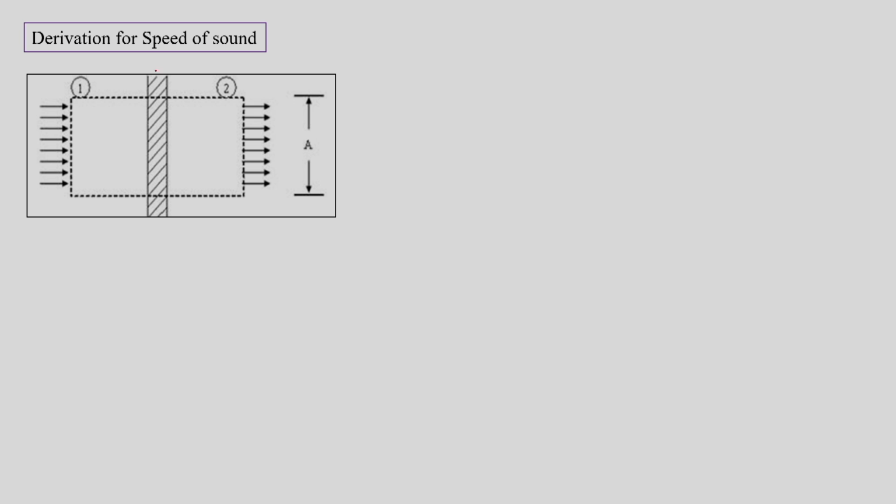This is, suppose, the wave which is a sound wave. Actually it is traversing with a certain velocity in a medium which is still, or has zero velocity, but we assume that the wave is standing still and the fluid is given the velocity of the wave.